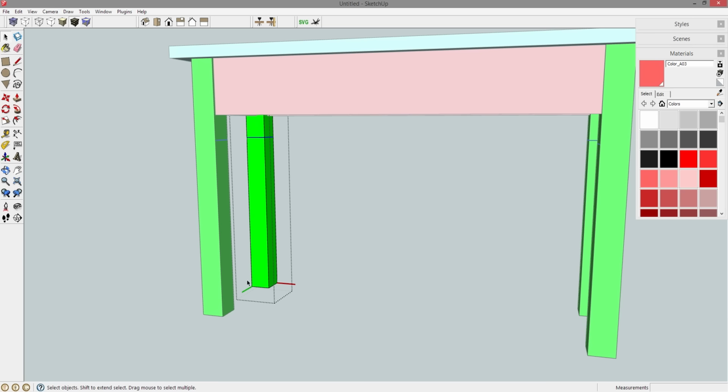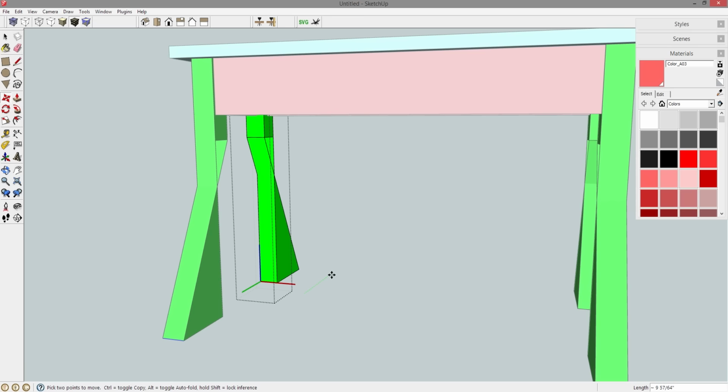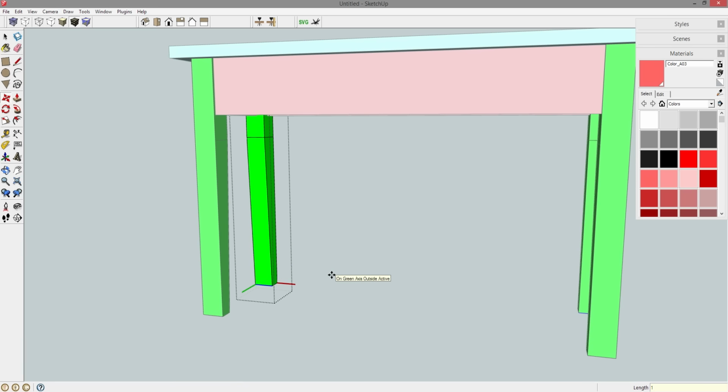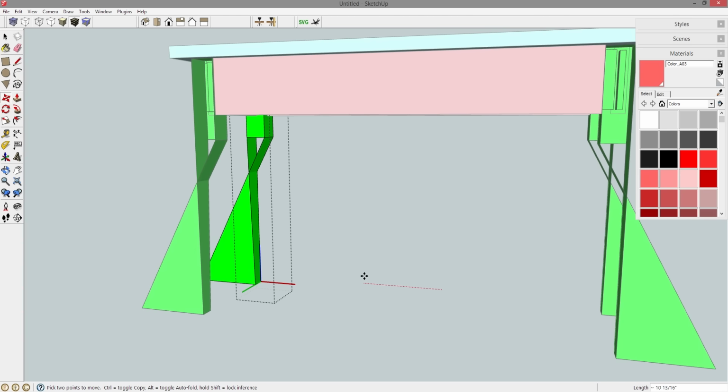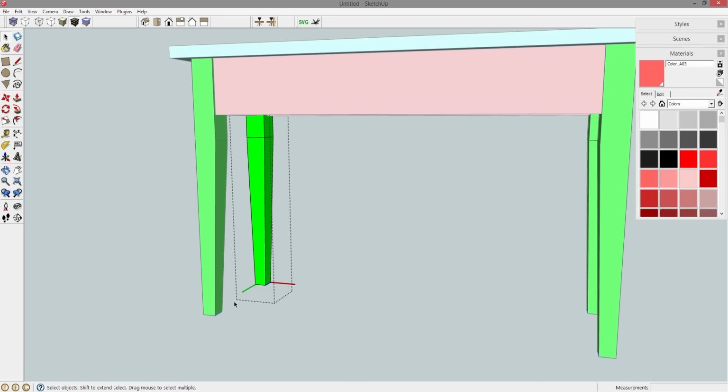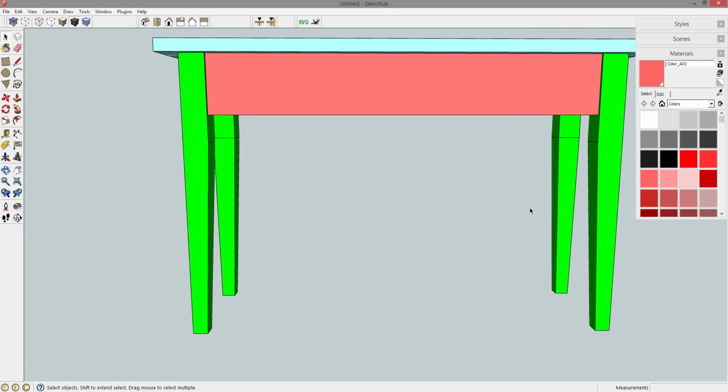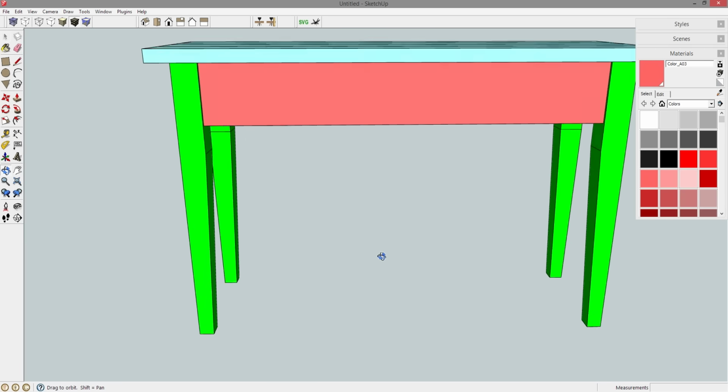And now let's make the taper. That just established the start of the taper. Now we can grab this down here, M for move, and let's push it in the green direction, 1 inch, enter. There's the start of the taper. The taper ends 1 inch in on the bottom of the legs. Select this other edge over here and do the same thing. M for move. This time we're going in the red direction. That way, 1 inch, enter. So now we have a 2-sided taper on both inside faces of all the legs, and they updated on the appropriate side for each individual leg.